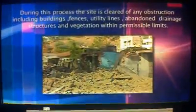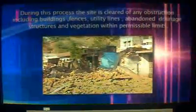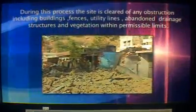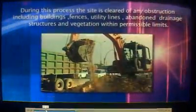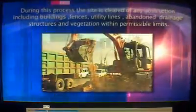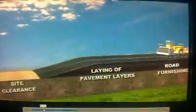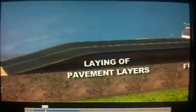The first process which is done prior to any constructional activity is called site clearance. During the process, the site is cleared of any obstruction, including buildings, fences, utility lines, abandoned drainage structures, and vegetation within permissible limits. The next step is the laying of different pavement layers.